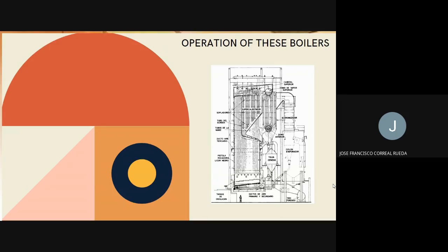Heat circulation. The heat transfer in the boiler is carried out by hot gases that result from the combustion. That heat passes to the water that circulates inside the steam generation tubes. The combustion gas passes the heat to the water circulating inside the steam generator tubes. The gases, as a hot fluid, transfer heat to the water both by convection and by conduction. The gases pass through the superheater tubes, transfer their heat, and then go to the steam generator tubes at a relatively lower temperature.